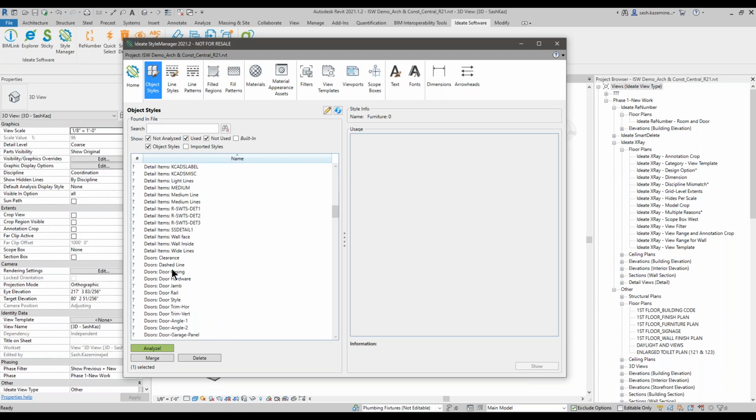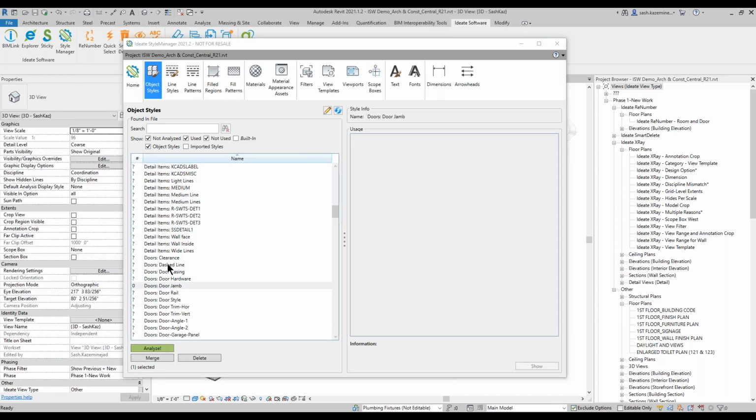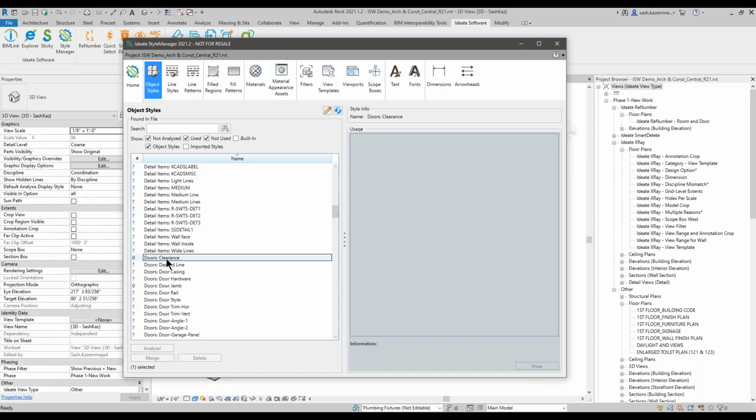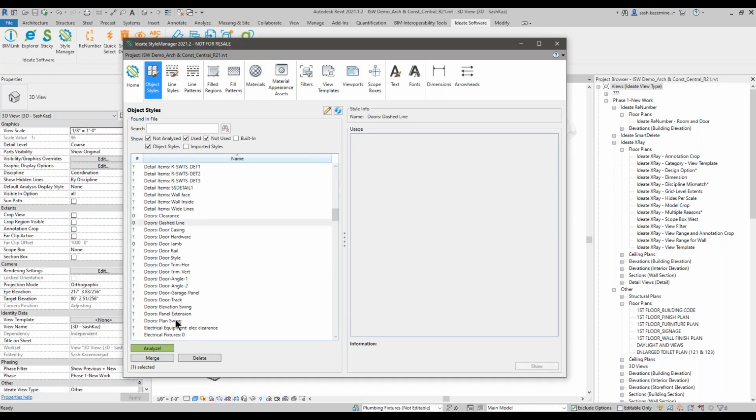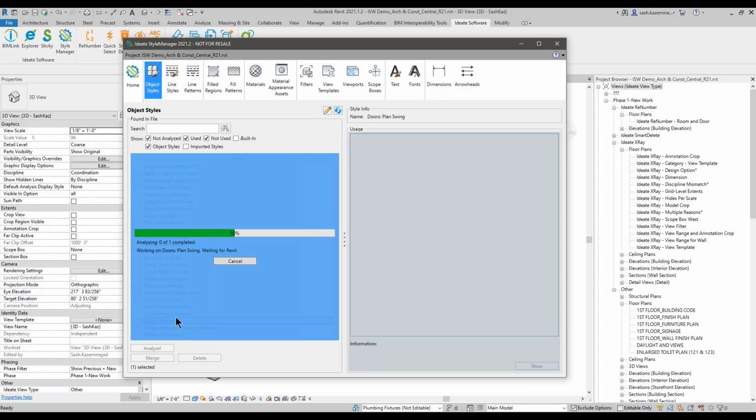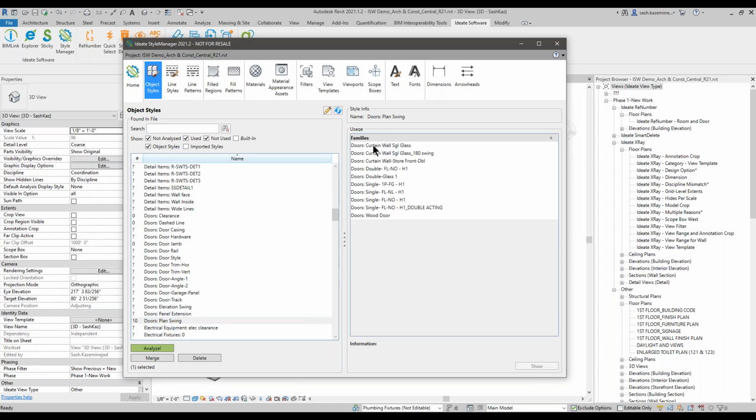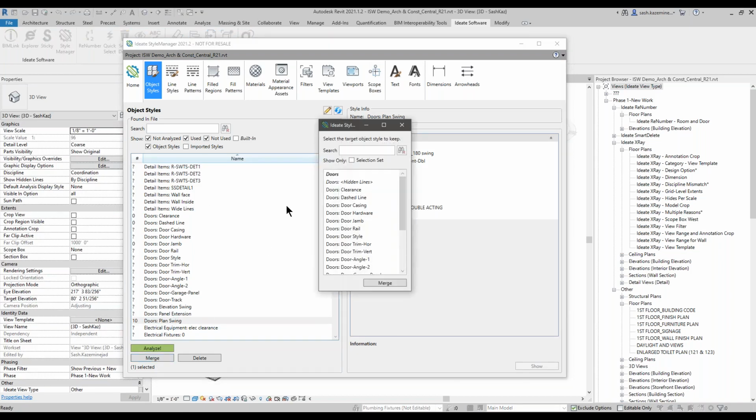It doesn't matter. Basically, any family you saw when Sash did the update in the first part of the presentation. If you wanted to save that family out to disk, you'd have to save the file via the project browser. Otherwise, if you imported it again, you're going to get that same kind of junk you got the first time, non-approved styles. How's that sound? Yep, exactly.